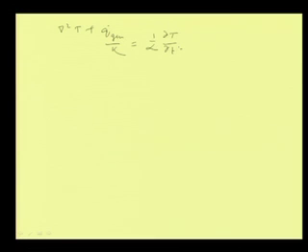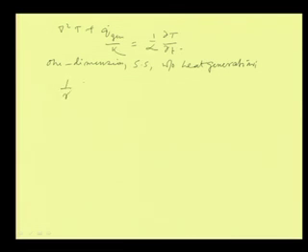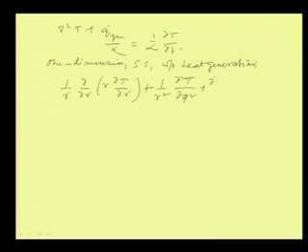Now, as we said, it is one dimensional and steady state without heat generation. Under that situation, this equation, the grad square term, I will write as 1 by r del by del r of r del T by del r plus 1 by r square into del square T by del phi square plus del square T by del z square, that becomes equal to 0.